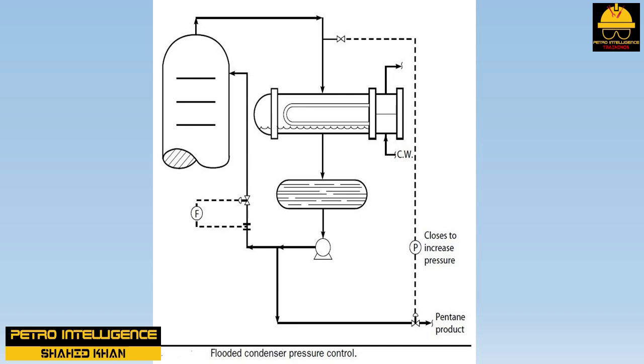Either way, erratic tower pressure results in alternating flooding and dumping, and therefore reduced tray efficiency. While gradual swings in pressure are quite acceptable, no tower can be expected to make a decent split with a rapidly fluctuating pressure.